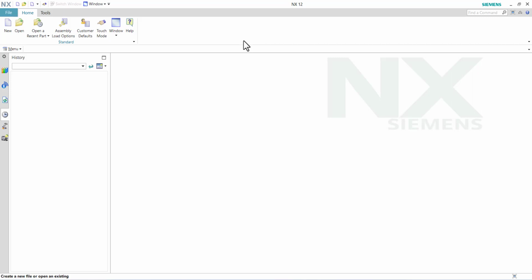When we want to convert a 2D sketch or a closed area into a volume, we can use the extrude command. At the same time, we can use this command for removing material from the body. So the extrude command can add material, or we can use it for removing material from your solid body.